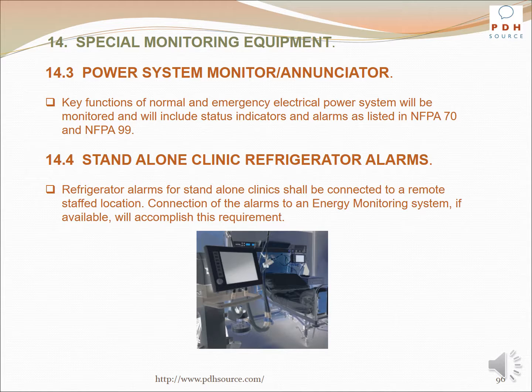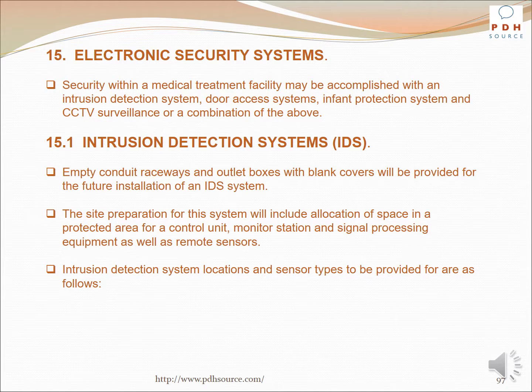For standalone clinics, refrigerator alarms shall be connected to a remote staffed location. Connection of the alarms to an energy monitoring system, if available, will accomplish this requirement.